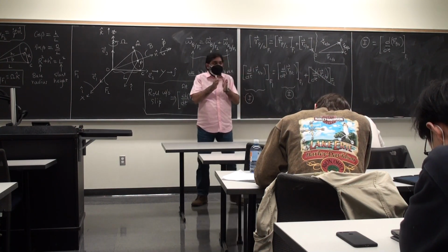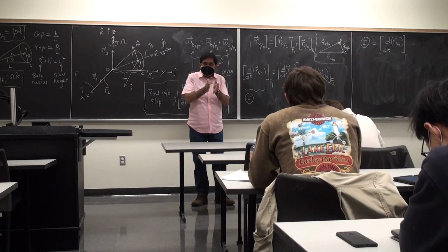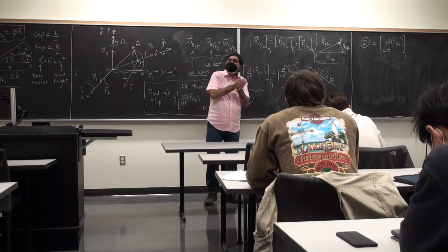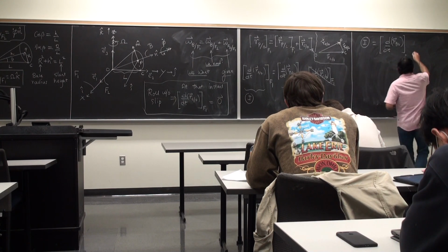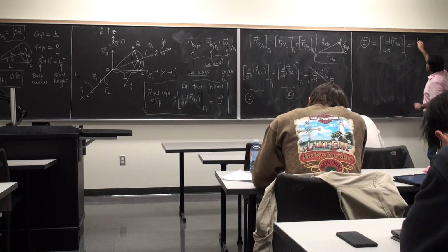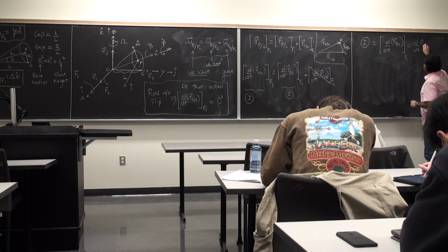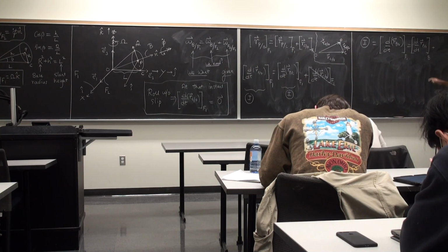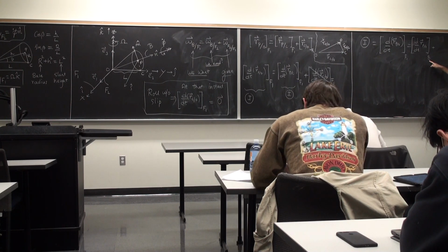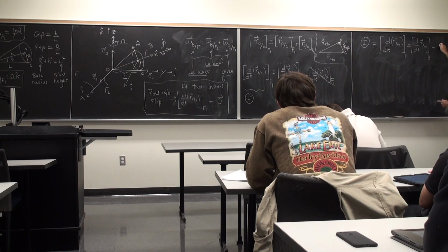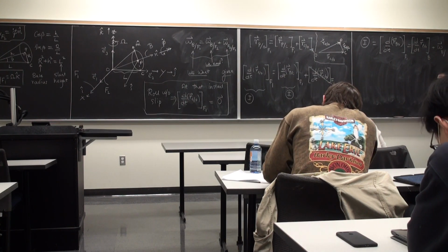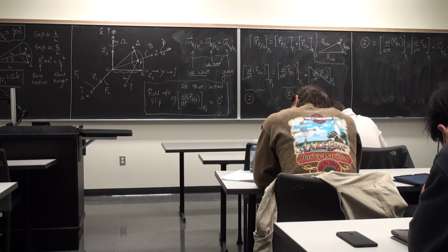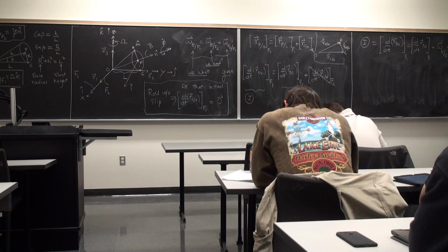So I'm going to write this rate of change using the body, and then taking the angular velocity of the body with respect to the frame F1. This can be written, once again something we proved last time, as d by dt with respect to the body. This is a choice that you can make; I can write this with respect to the frame F2 as well. If I choose it with respect to the body frame, then I have to write this as omega of B slash whatever frame I'm doing the time derivative in, cross with R P slash C.